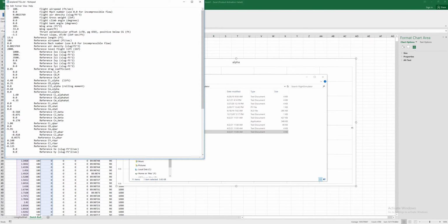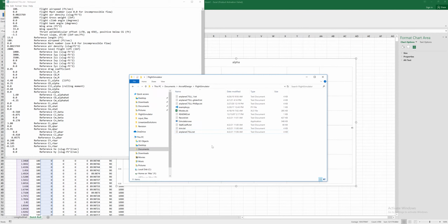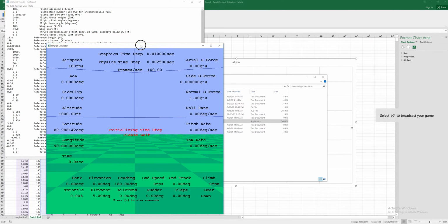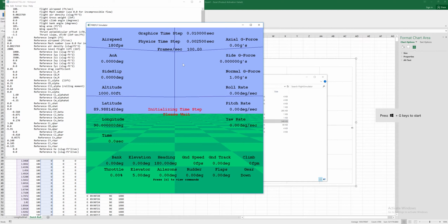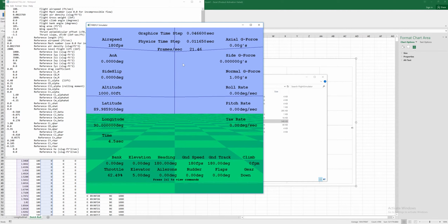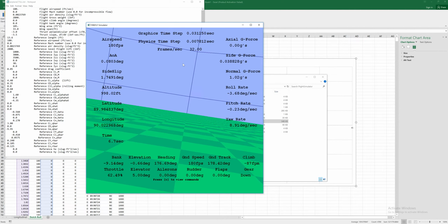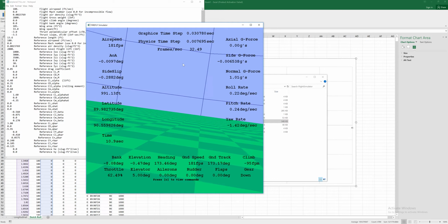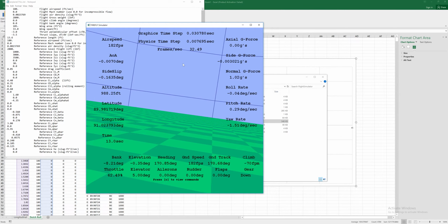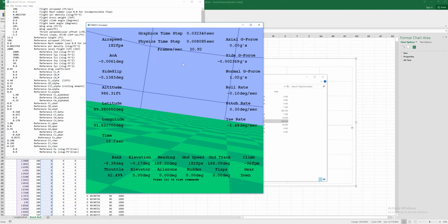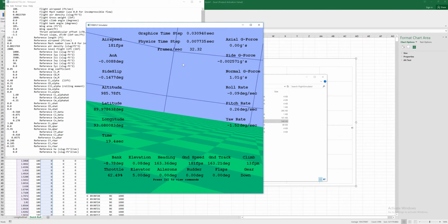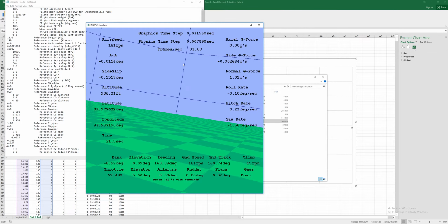And now let's rerun the sim. We're going to try to repeat the same thing as we did last time. I'm just going to put in a rudder kick really quickly, and we're just going to watch the response of the aircraft. You can see that the Dutch roll was a little bit less fluid. It was a bit more stiff. That's because we increased the spring constant about the yaw axis, basically, this yaw stability.